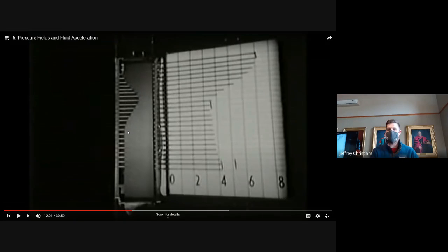The same thing is going to happen here. Fluid's going to come this way and come up, and then boundary layer separation is going to happen because pressure gradients are winning over viscosity. And what you're left with is this shape will leave a big wake. In this region here, you'll get turbulence and mixing. Basically the fluid is going like this, with all the viscosity from those fluid layers rubbing against each other, causing heat.